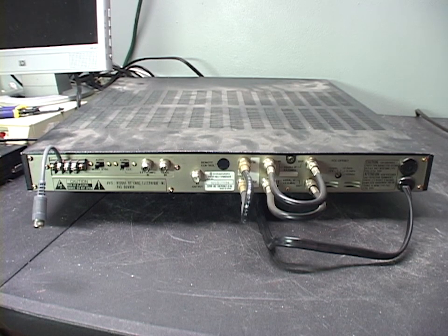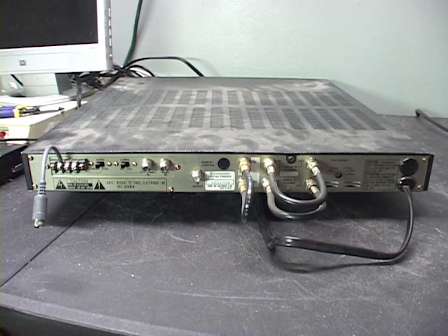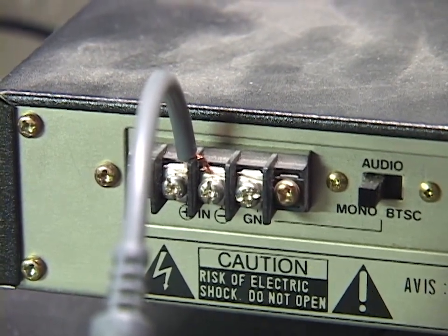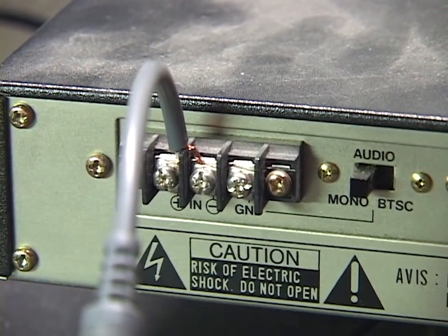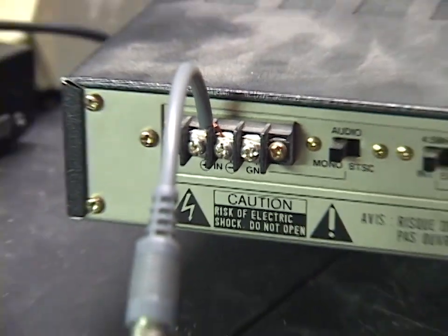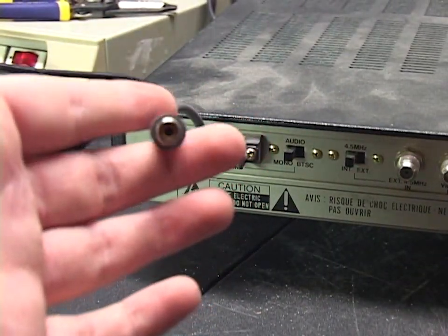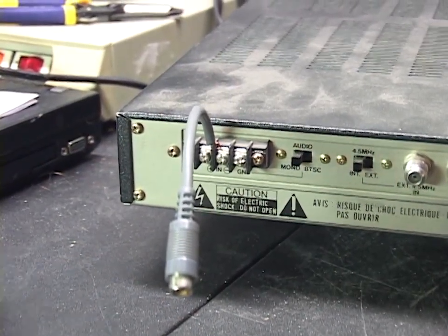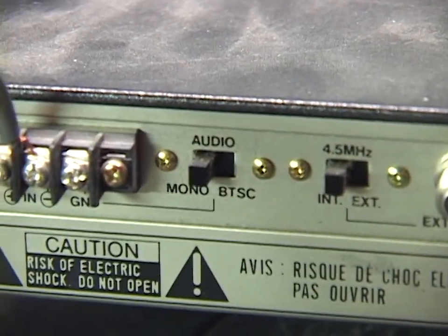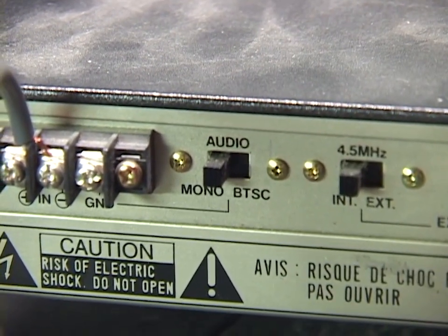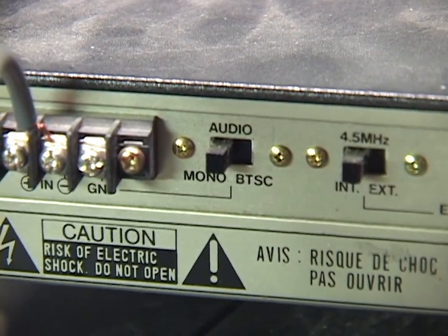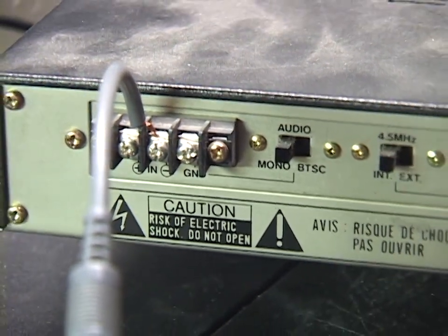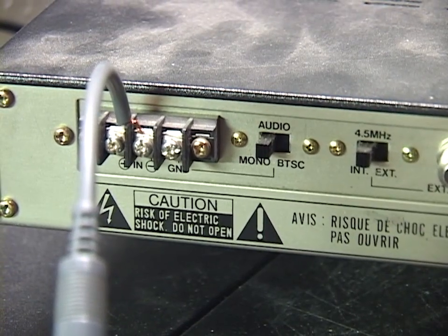So things get a bit weird on the back of this thing, but I will do my best to decipher everything. Starting at the far left is our audio input, and you can see it's not an RCA jack. Nope, not on broadcast equipment like this. It's screw terminals. So what I've done is I just cut a female RCA pigtail and screwed it onto those screw terminals. And you have a switch to go between mono audio and BTSC audio. BTSC was just some sort of other audio standard that your cable system might have required. I think it changes the levels and the EQ and stuff like that.